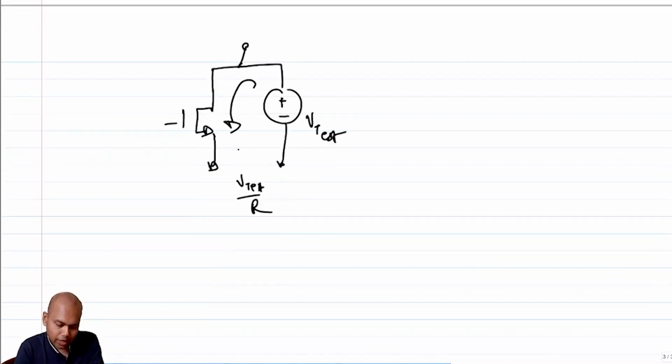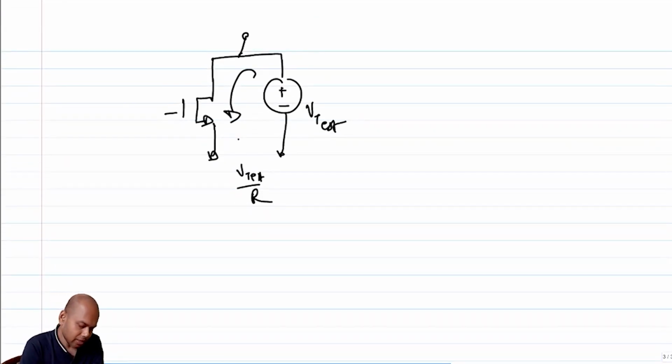So what do we need to do to the gate? Note that what am I aiming for? I am aiming for increasing the drain voltage, right? While I am increasing the drain voltage, the drain to source current should increase. And if I neglect channel length modulation, the only way I can ensure that is if I also increase the gate voltage, right? So if this increases, this should also increase. And this is typically done by short circuiting the drain and the gate. This is a diode connected transistor, right?